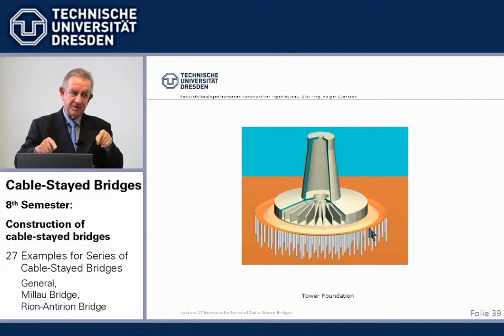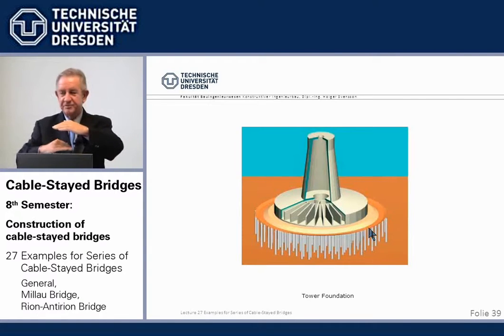It's not the first application at all. I've given you the reference, but it's the first for bridges. I think it has been done for buildings or something. And it has also been used, you may recall the Golden Ears Bridge in Vancouver, BC, which I showed you. It's an extradosed bridge by Bilfinger, lately completed, where I was checking engineer. And they have also taken this because there's also the earthquake. Plastic movement within the gravel layer to take up the up to 2 meters.